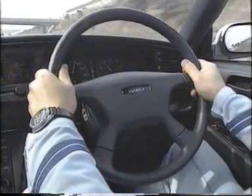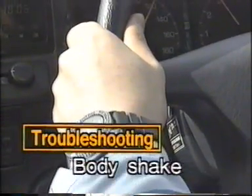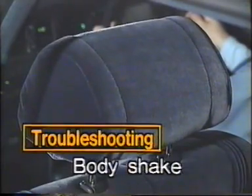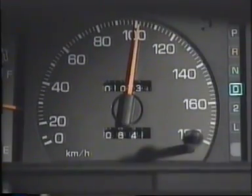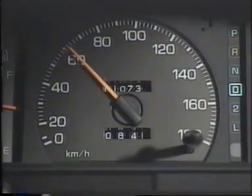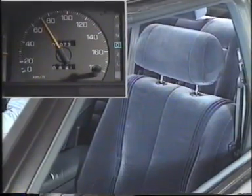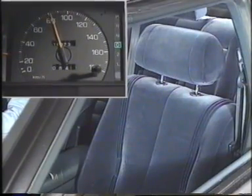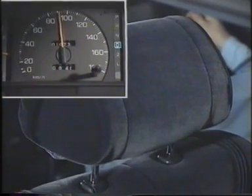We will now study actual troubleshooting using two cases as examples. One of the two cases concerns body shake. The first step of troubleshooting is test driving the car to confirm the phenomenon. You need to know the relationship between the body shake and the vehicle speed. In this case, you first begin to notice vibration when the vehicle speed rises to approximately 80 kilometers per hour, and the vibration increases as the speed increases to between 90 and 100 kilometers per hour.